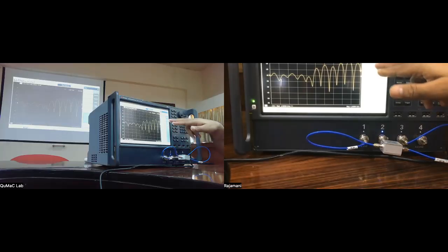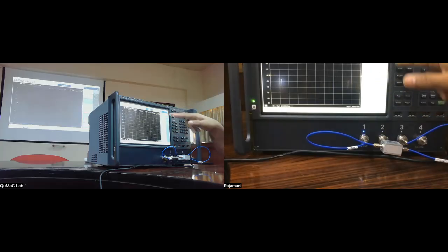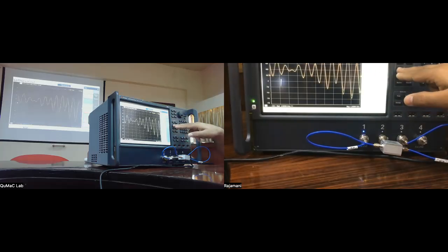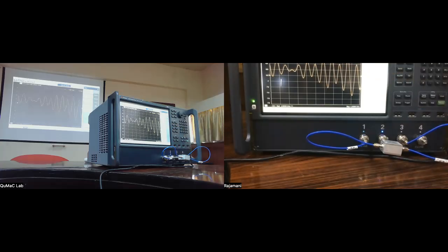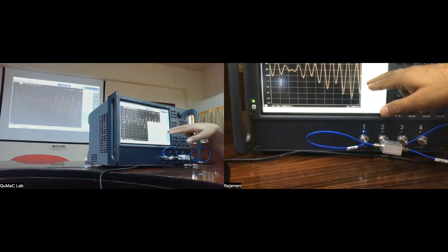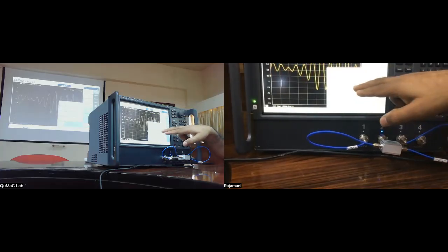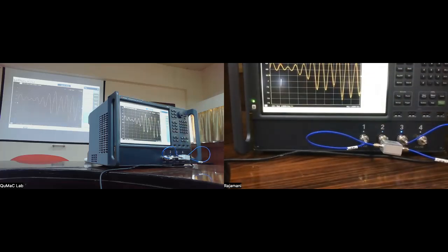And it's also a reciprocal device. So the lossy part doesn't make it non-reciprocal. So S21 is the same as S12. In fact, here they are quite well mapped. Similarly, if I look at S32, put that to memory, and compare that with S23, same. So it's again a passive network.